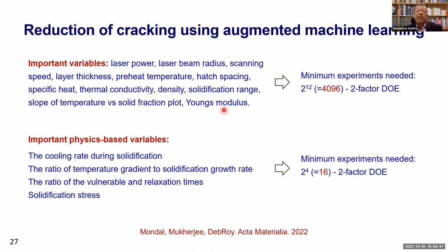How so? Think of the flow of a fluid through a pipe of circular cross section. If you wanted to know the structure of the flow, laminar or turbulent, you will need to know the diameter of the pipe, you will need to know the velocity of the fluid, you will need to know the density and the viscosity. So how many variables? 4 variables. But someone who has studied fluid mechanics will say, I don't need 4 variables. I can use just the Reynolds number.